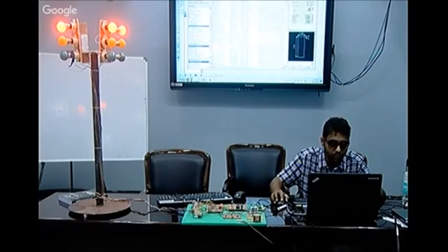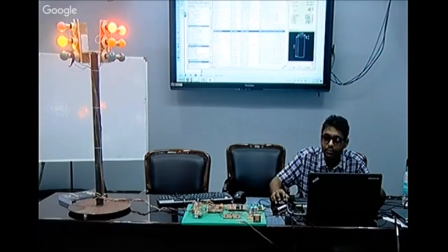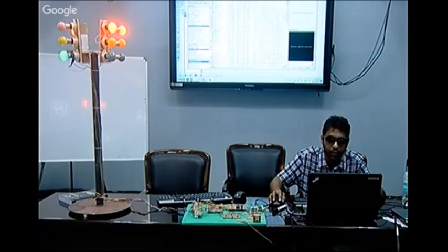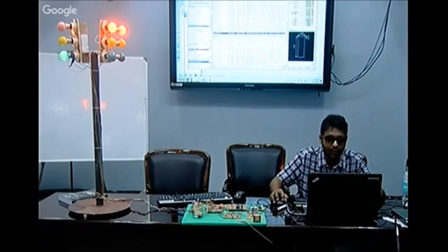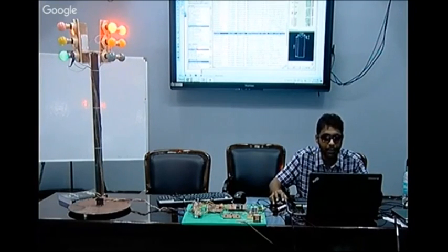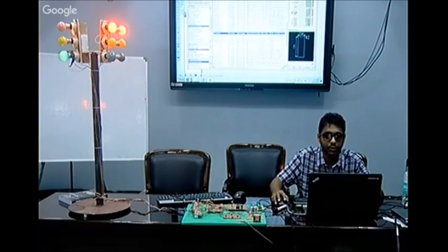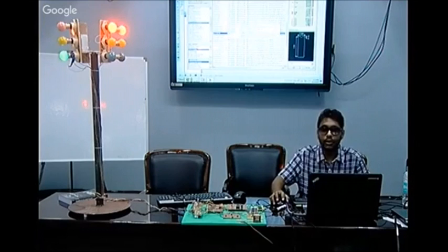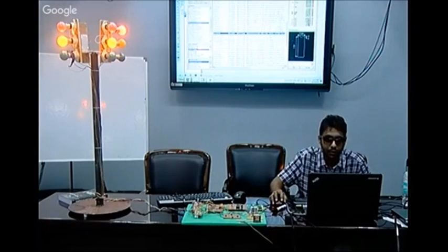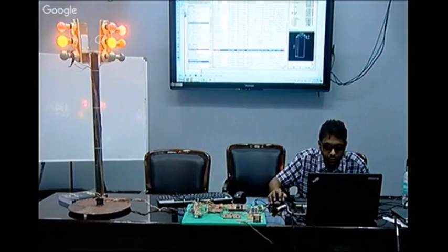So we have to search. If you select microprocessor ICs, it has further subcategories: which microprocessor, which family, 8051, and it will display only 8051. Let's try to find components with this method only. If you search this way, it will increase your capability to learn the different types of components. So select 89C52.